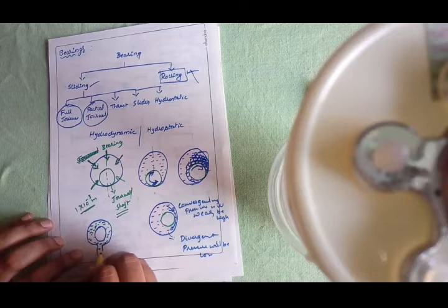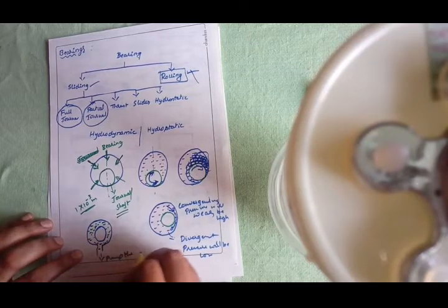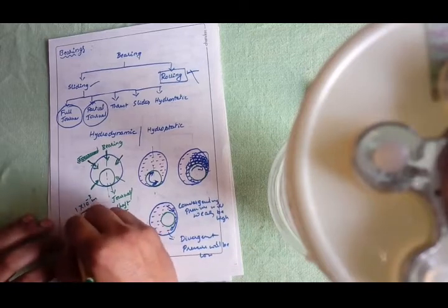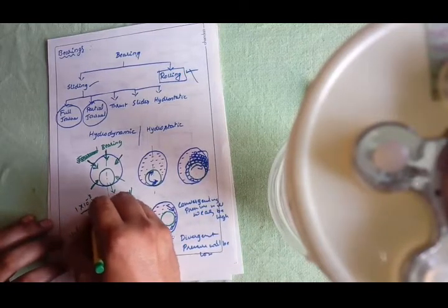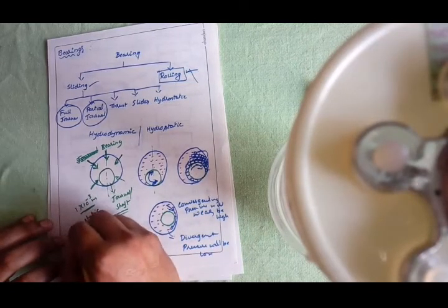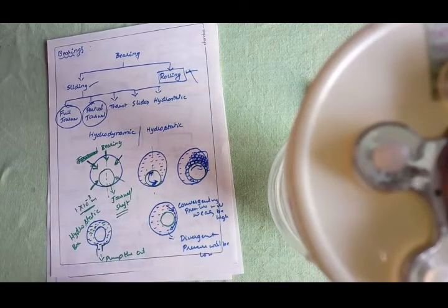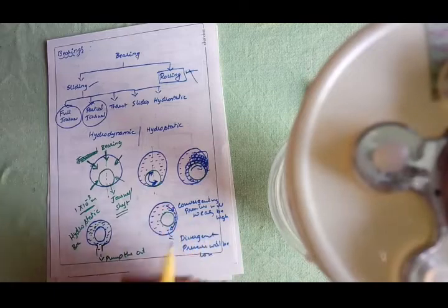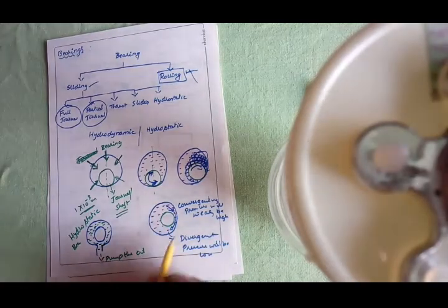Here you need the pumping equipment; you need to have a pump and a separate mechanism for pumping the oil, whereas for your hydrodynamic bearing, no pump and no extra devices are essential. If the oil is continuously available, it is going to build a thick film of oil between the journal and the bearing.